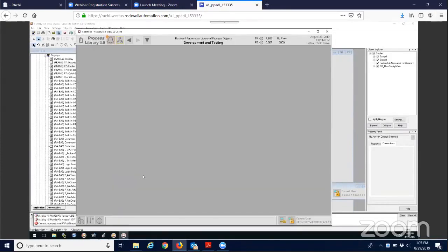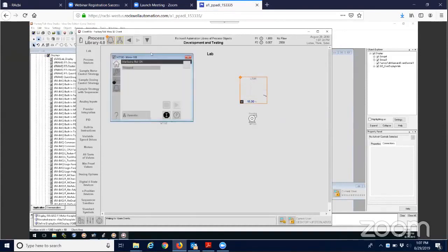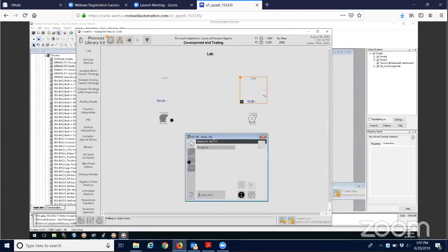This becomes very important as you start growing the size of the system and we start looking at different areas and different HMI servers. You don't necessarily want your operators to have access to everything. Maybe you just want them to have line 1. So this gives you the ability of taking one big application and segmenting it into smaller sections. As they go into that specific area or lineup, think of it like the boiler, I'm only presenting the information for that boiler, not everything else.